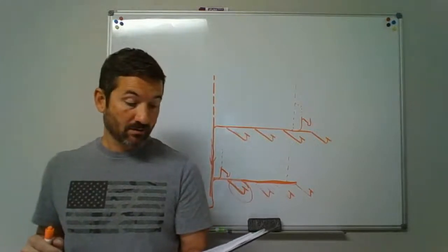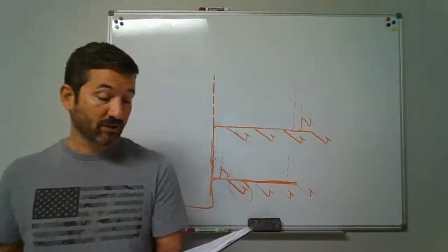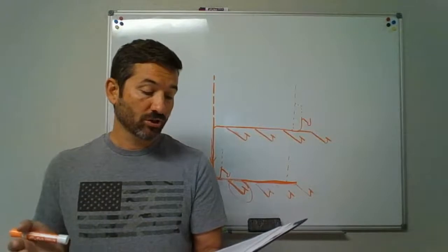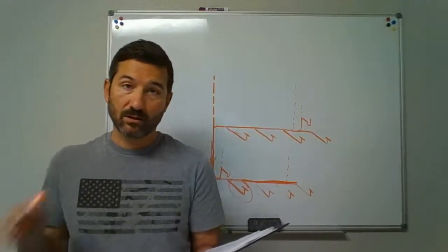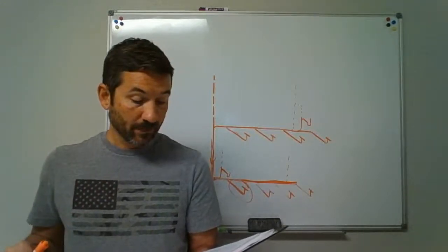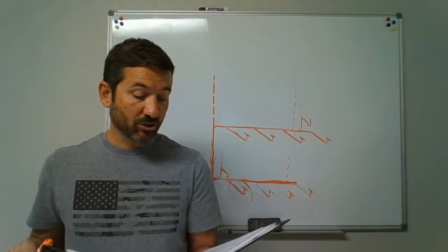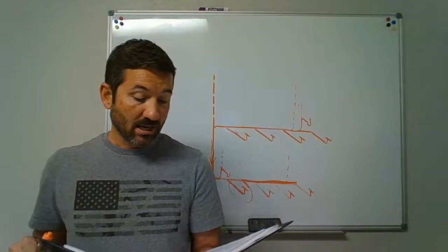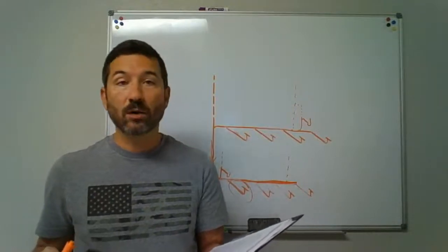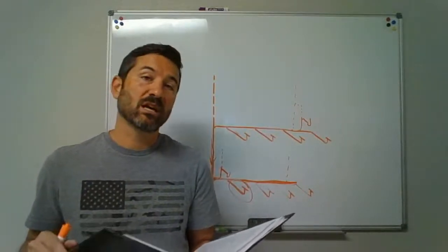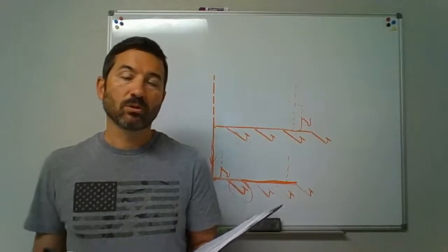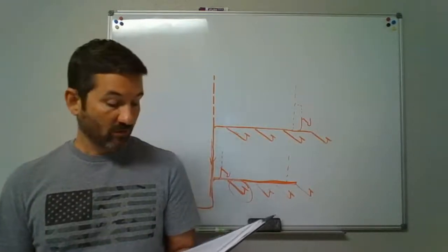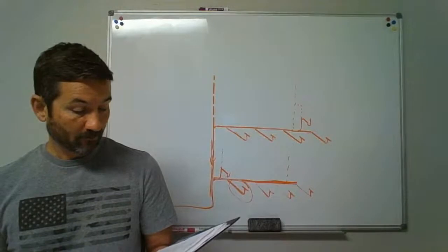Additional fixtures in there. Fixtures other than the circuit vented fixtures are permitted to discharge to the horizontal branch, so we can tie other stuff into that horizontal branch. Such fixtures should be located on the same floor level as the circuit vented fixtures, and shall either be individually or common vented. When we tie them in, we'll pull another vent off and vent those out separate, and that's fine.